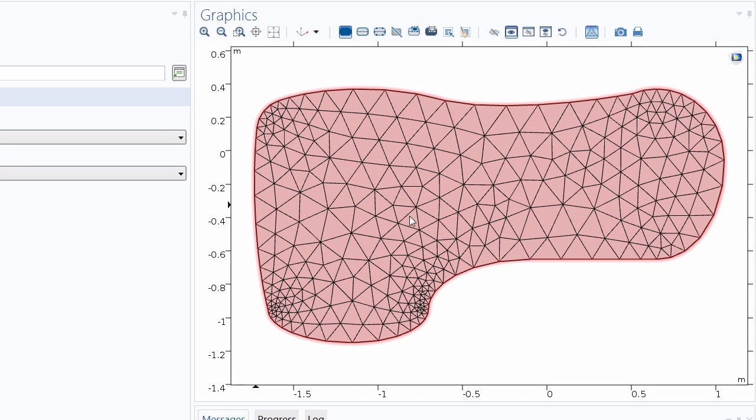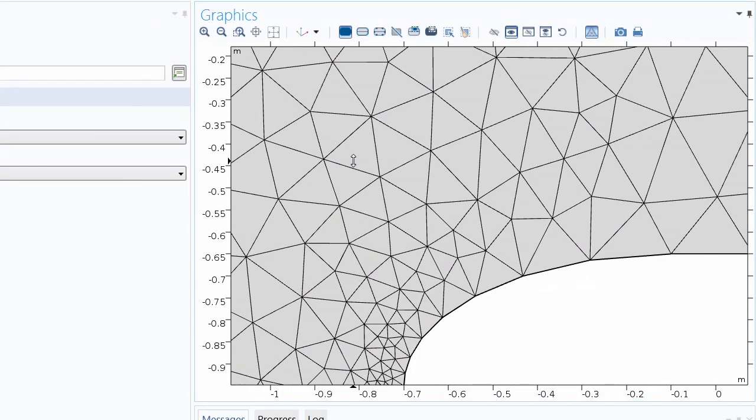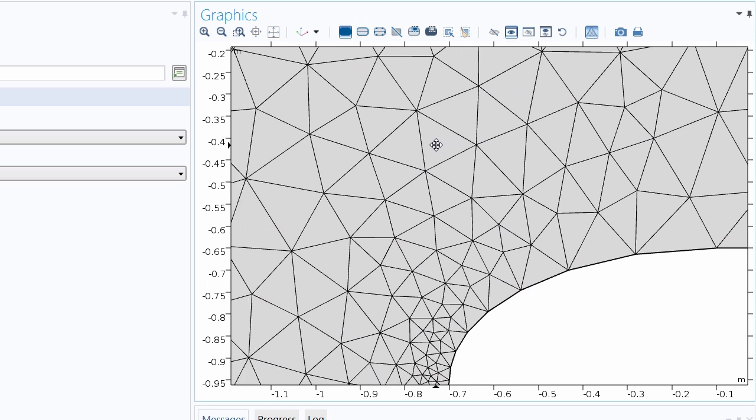And by discretize, we mean to break down into smaller, discrete parts. This happens through the geometry being divided into several smaller, discrete parts called elements. And the solution is obtained through stitching together low-order polynomials over each element to form a piecewise global function.